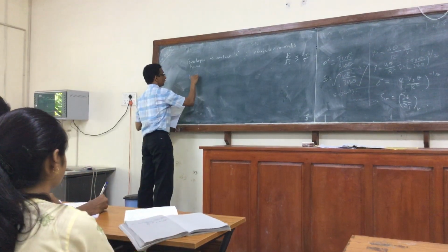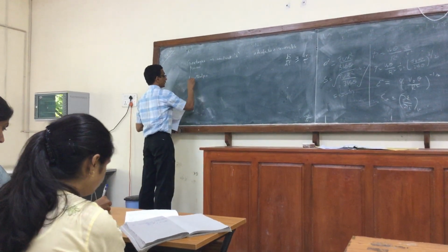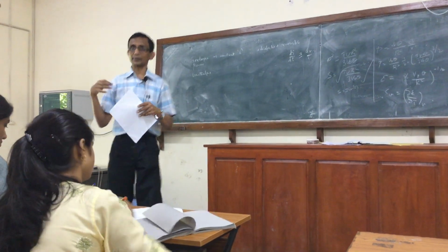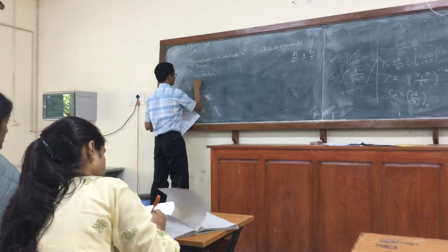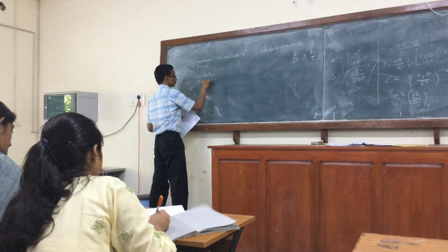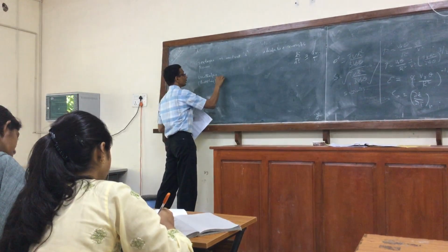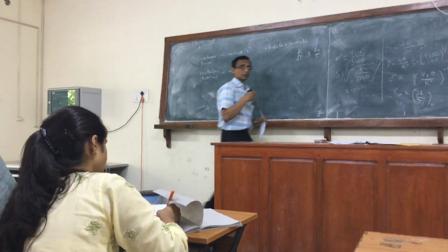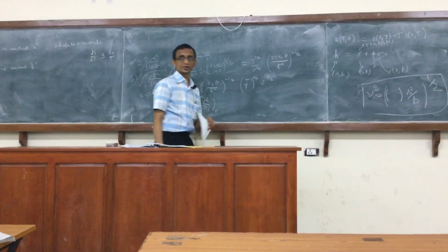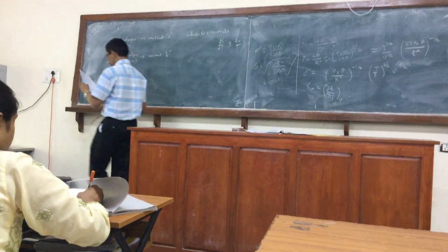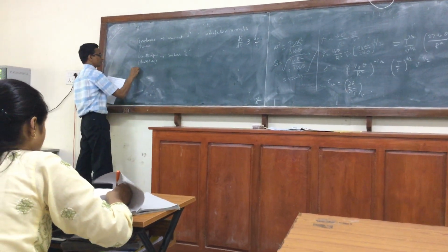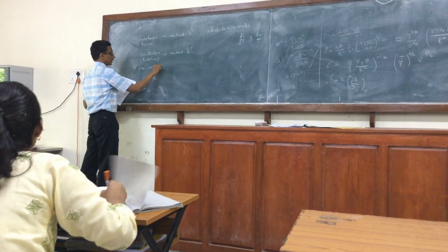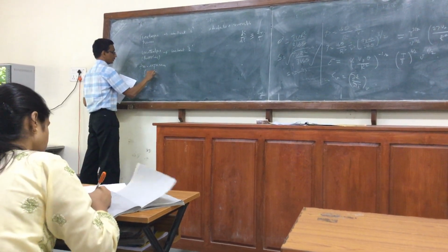So then what we have is an isenthalpic process, which is often referred to as a sudden expansion in the flow process. Sudden expansion is called a throttling process. Constant H, we have already seen one example through the Joule-Thomson coefficient. The other one that is given is what is called a free expansion. That is generally taken to be a constant E process.